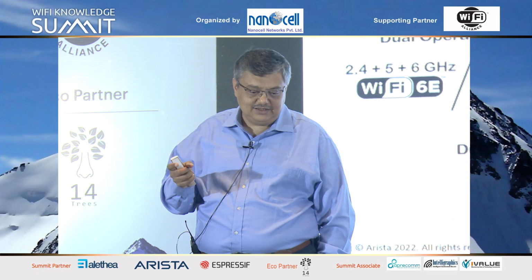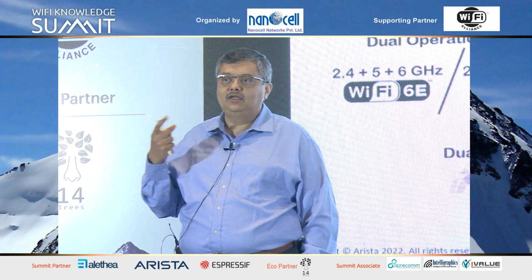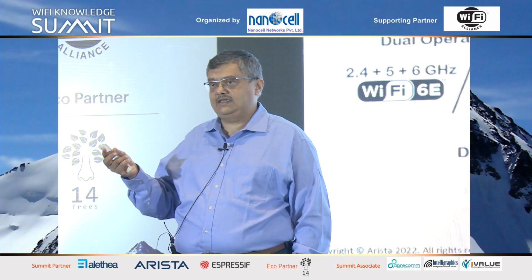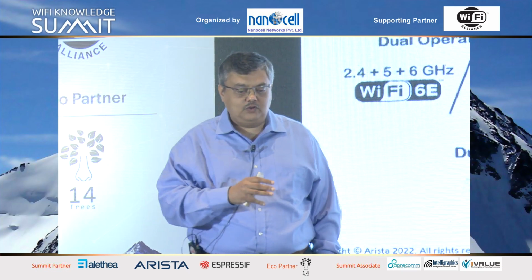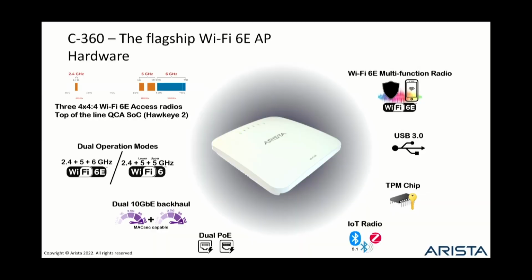There were a lot of challenges in this. The filtering that needed to be done, the way the separation between the 5 gigahertz radio and 6 gigahertz radio had to be done. There were quite a few challenges that we saw here. The other thing is that there is a mode of operation for this AP that runs in 802.3at mode as well, where we dumb it down a little bit so that even if you provided 802.3at power, it does function in a very reasonable manner. It gives you the kind of experience that you need. Obviously, it doesn't do everything else.